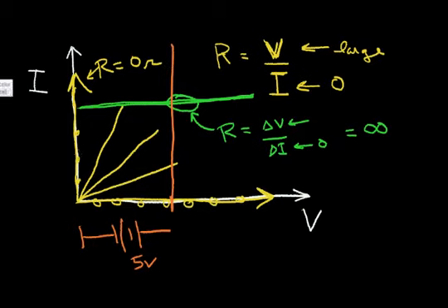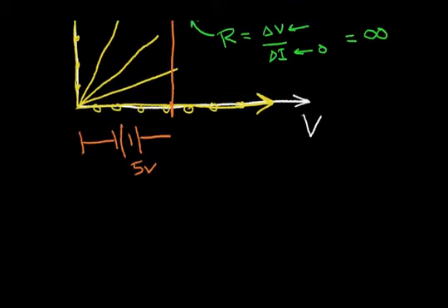So when I plot the MOSFET transistor, let me scroll down here, I plot current versus voltage. There's a resistor region. Then the resistance increases and it becomes almost a current source, which is infinite resistance. Then eventually it breaks down. So let's first relate this resistance region of the curve to what's going on inside the channel of the N-channel MOSFET transistor.